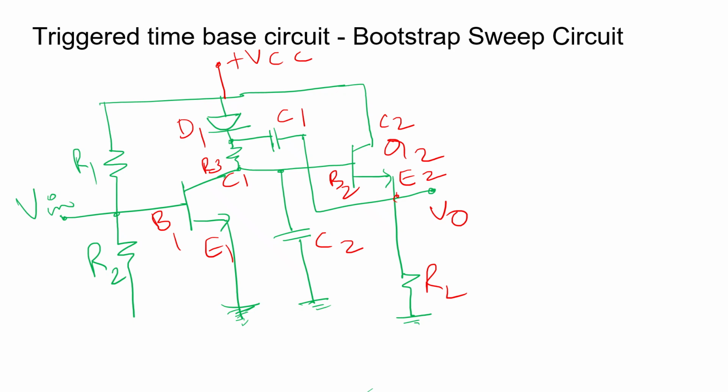Both the transistors are NPN transistors, namely Q1 and Q2. Transistor Q1 acts as a switch in the circuit, and the transistor Q2 is fitted to act as an emitter follower. The diode D1 is present here for preventing the discharge of the capacitor C1 in the opposite way. The resistors R1 and R2 are present for biasing the transistor Q1 and keeping it turned on by default.